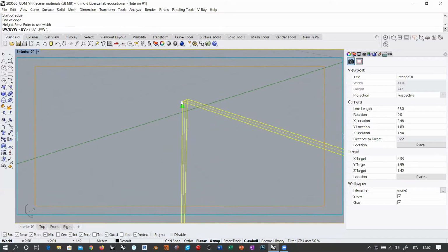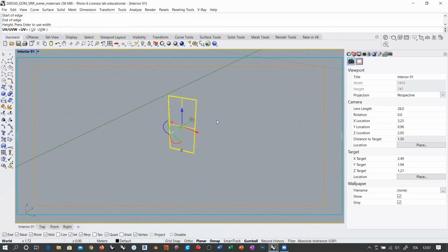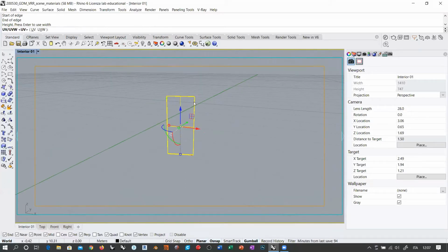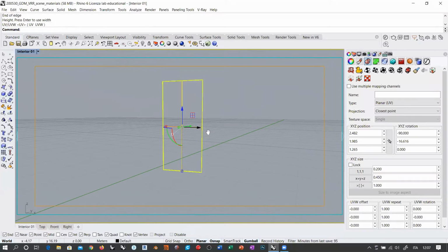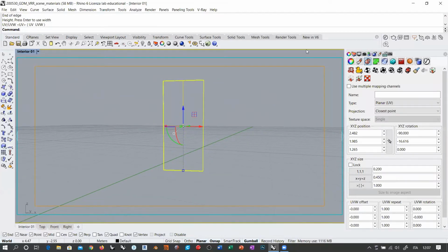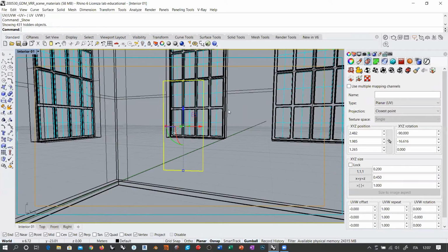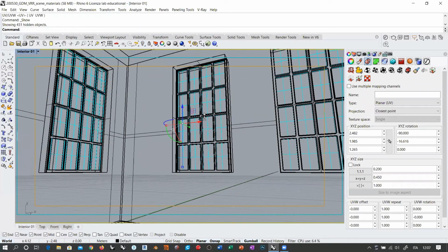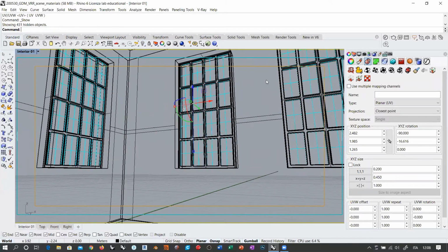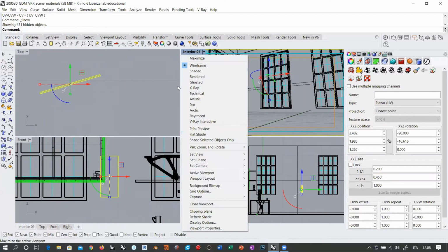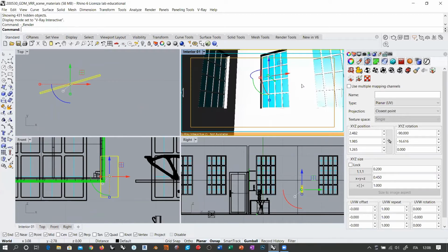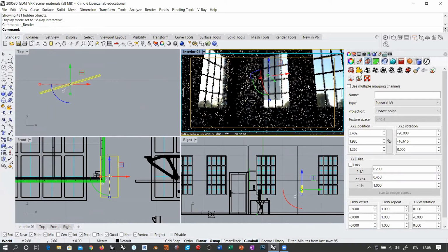Now, one problem is that our texture is more or less square, while my glass panel is more or less vertical rectangular. So I am stretching in this moment the texture vertically quite much. So the fingerprints will be stretched vertically, okay? But it doesn't matter, it's just for, let's say, starting to work with this kind of techniques. So bear with this. So I'm going back to this situation, and I'm going back to a V-Ray interactive render. Let's see if we start seeing something already.